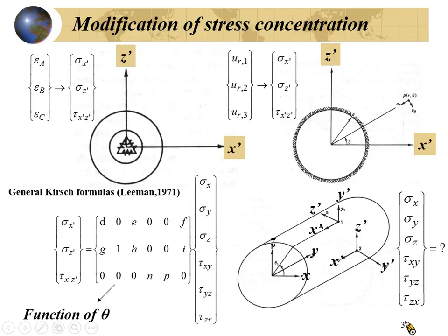Usually, for stress measurement, we want to have some redundancy. What is redundancy? We will try to use 9 equations to solve the 6 variables to eliminate possible error. So usually you will measure at 3 different locations.